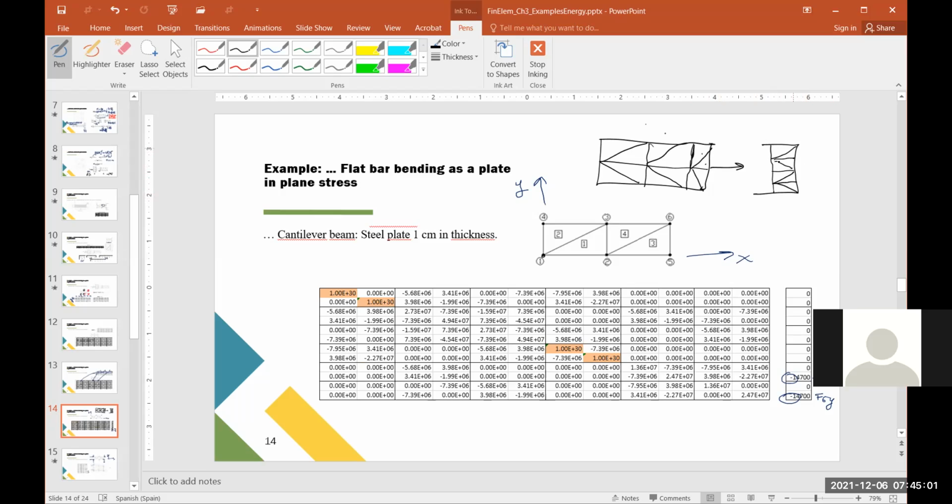So you see that you have more elements in this area, and they are smaller, in the place where you apply the force. So in this case, you can calculate in a better way the distribution of stresses around this area, if this is the area where you want to analyze the stress distribution. And then you can increase the size as we have done here.